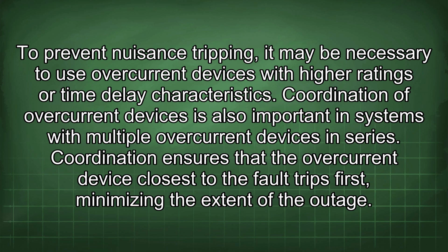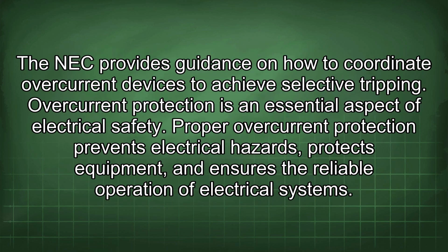Coordination of overcurrent devices is also important in systems with multiple overcurrent devices in series. Coordination ensures that the overcurrent device closest to the fault trips first, minimizing the extent of the outage. The NEC provides guidance on how to coordinate overcurrent devices to achieve selective tripping.